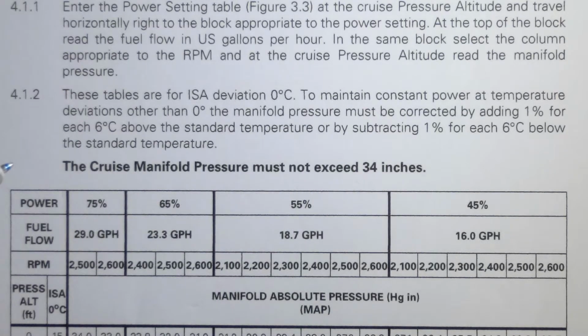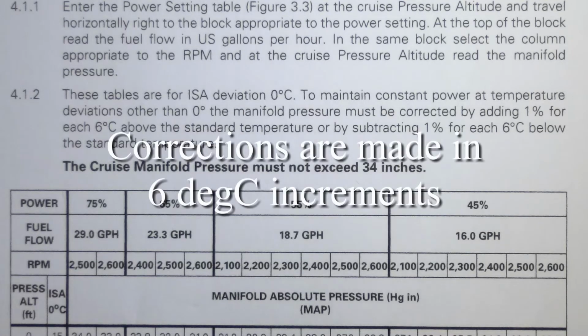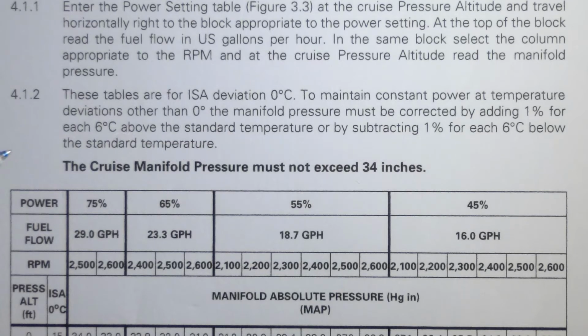Now what happens if the temperature deviation is something other than 6 degrees Celsius above or below? Let's say you're 2 degrees Celsius warmer than ISA. Well, we only make adjustments in 6 degrees Celsius increments. So if we're warmer than ISA by 6 degrees Celsius, we'll make an adjustment. If we're 7 degrees Celsius warmer than ISA, we'll make the adjustment for 6 degrees Celsius deviation.